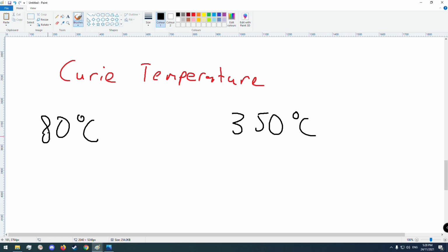It can be very easy for a neodymium magnet to get up to 80 degrees Celsius as well in speakers, as for example, I live in Australia, and a temperature delta from say 50 degrees Celsius on a hot day in a hot car in the sun, even with the aircon on sometimes, means that it only requires a 30-degree temperature delta before the magnet could potentially stop working, which isn't that much power going into a speaker at all.